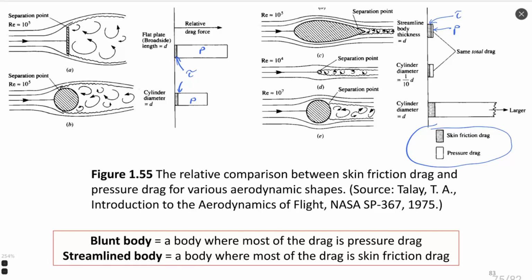You remember that it's constant for all points inside the flow, because the flow is adiabatic, there is no friction, right? And it's isentropic. So this Bernoulli equation works quite well. And pressure is simple to determine, simple to calculate analytically. So we can also calculate drag analytically in such a way.